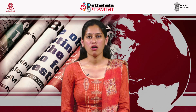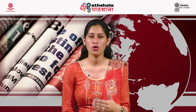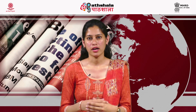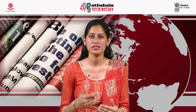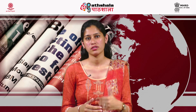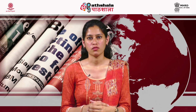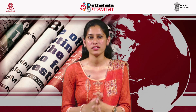So it can also lead to more photosynthesis and the development of more plants, and more live plants seems like a good process at first glance, but more live plants means more dead plants which are piled up at the bottom of the water bodies and increase the biological oxygen demand, as more bacterial population will grow and utilize the oxygen to decompose that organic matter. And more biological oxygen demand cannot be afforded in the water bodies, as thermal pollution already reduces the dissolved oxygen content in the water body.